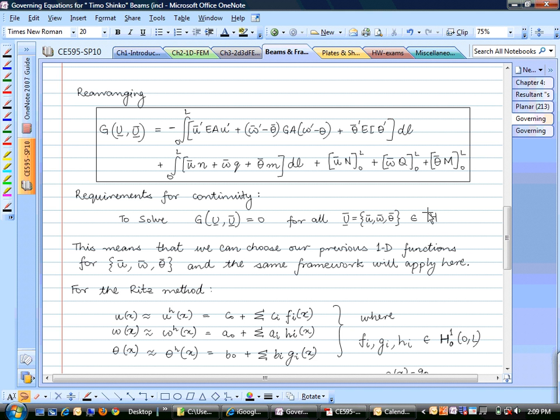H10, yeah, square integrable first derivatives. And the reason that we needed square integrable first derivatives was because in our weak form, this was the one-dimensional weak form that we had obtained in chapter 1, there are derivatives to the degree 1, and therefore for this integral to be well defined, this derivative squared itself needs to be well defined. That's why this needed to be H10 in that case. So what should it be here?